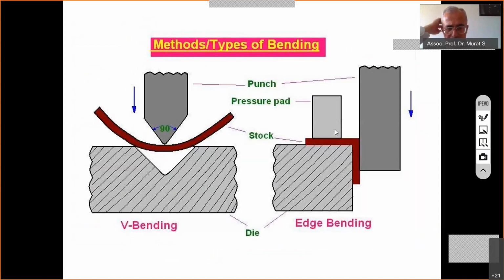It shows the folding, bending stage. Okay, we use special points and special dies. Knowing the theory and also the engineering experience about sheet metal work, we fix what should be the, say, minimum folding angle.